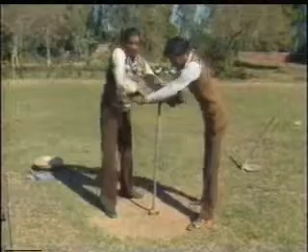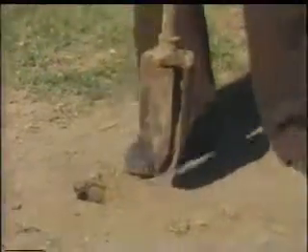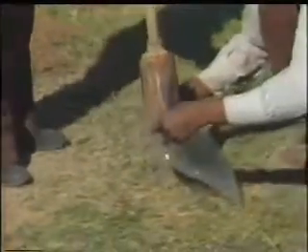The soil removed from the auger in each lift is deposited in individual stockpiles in an orderly sequence. The information so obtained may be used to plot borehole log. Augers operate best in loose, moderately cohesive moist soils. In dry soils, water is added for easy advancement of auger.